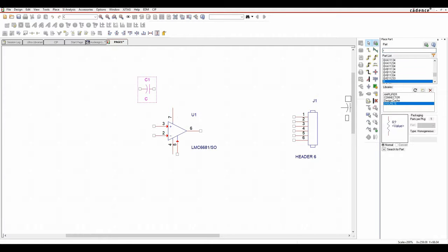Here we want an R. So I'm basically going to have one on the positive, one on the negative, and you can just drop the pin-to-pin connection to actually make connectivity here. And then once the resistors are placed, you can literally just drag them apart. So I can take it all the way across, connect it to pin 4, and I've made connectivity there. So you can just drag resistors around to make the connectivity, which makes it a little bit quicker than actually drawing the wires, which can be really helpful.